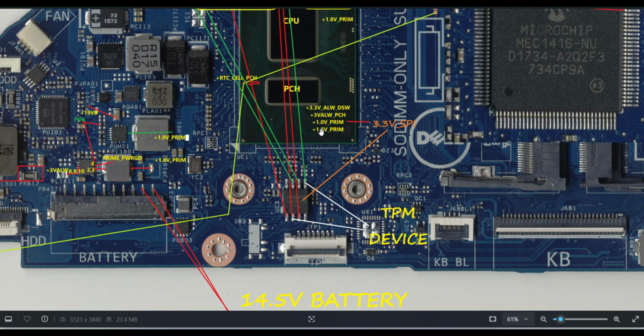See, as we know, here it is 3.3 volts always PCH. This will convert to 3.3 volts underscore SPI. Through this signal only, the BIOS chip will become active. The main supply, meaning the voltage, will come from this particular signal. Once it enters, these are the pins.